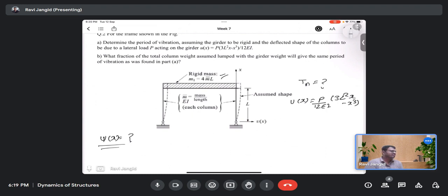If you read the shape function in FEM or somewhere else, if we have two nodes and we know the deflection at these nodes, we can find out the value of unknown u within the element with respect to these nodal coordinates. Did you get it? Yes. So that we call a shape function.